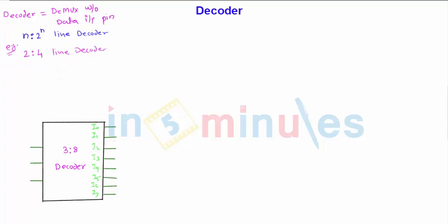In such a way you can also find a 3 to 8 line decoder. What we have here is the example of a 3 to 8 line decoder. This box basically represents an IC. For this IC, we have 2 pins, which you can call the plus VCC pin and the ground pin, to activate the IC. Plus VCC is logic one, which works on a plus 5 volts DC supply, and the ground is provided here to activate the IC.